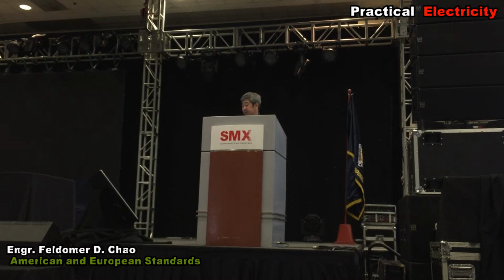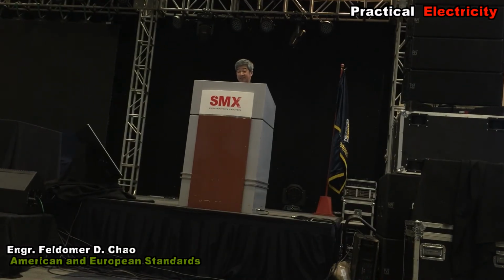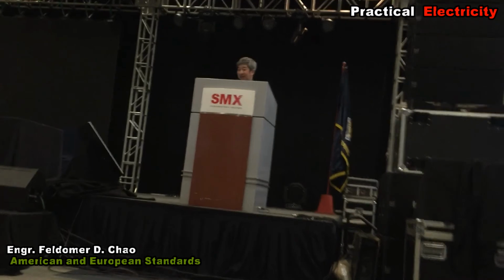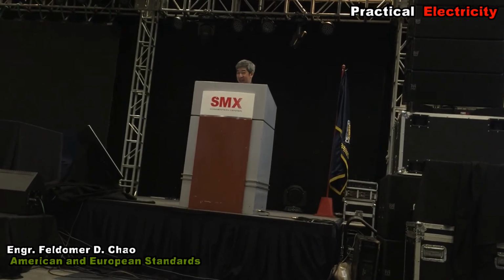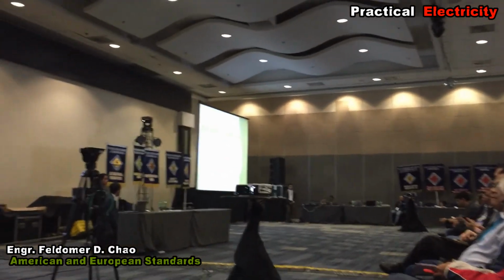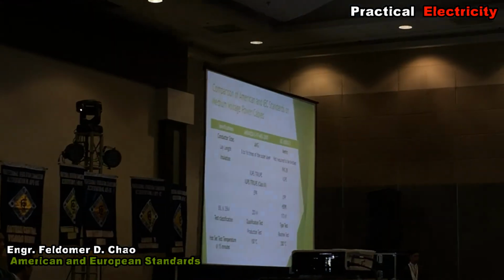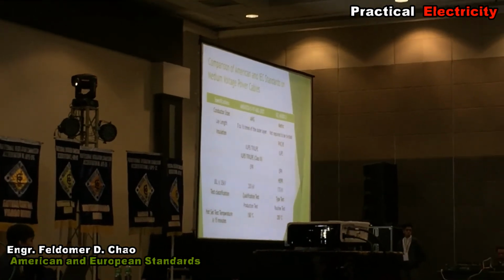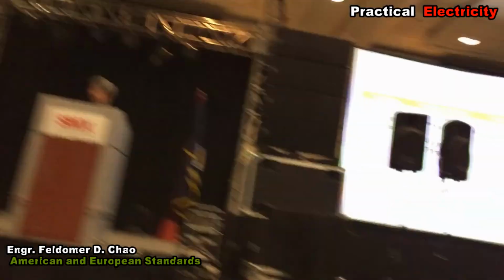medium voltage cables. Their wire sizes, nothing will really match. You have an AWG one and a metric size. It's not gonna match really. So if you're gonna use IEC cables, mainly you're gonna get something which is a bit higher. If the original standard is American, you're gonna get a size which is a bit higher than the previous American standards.